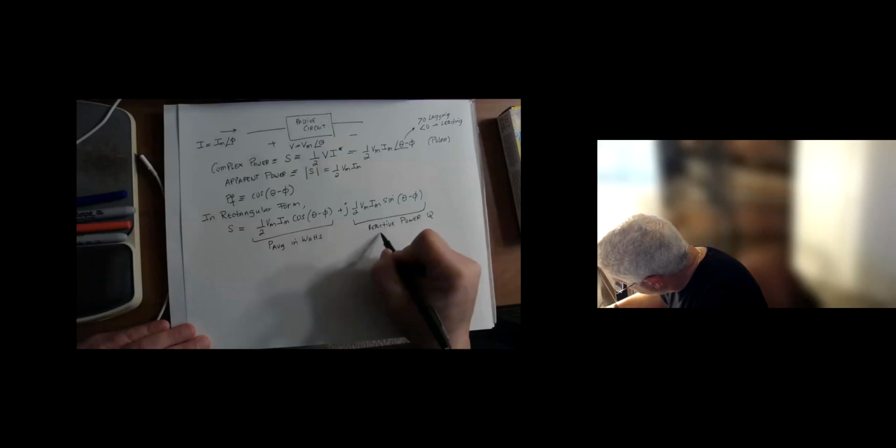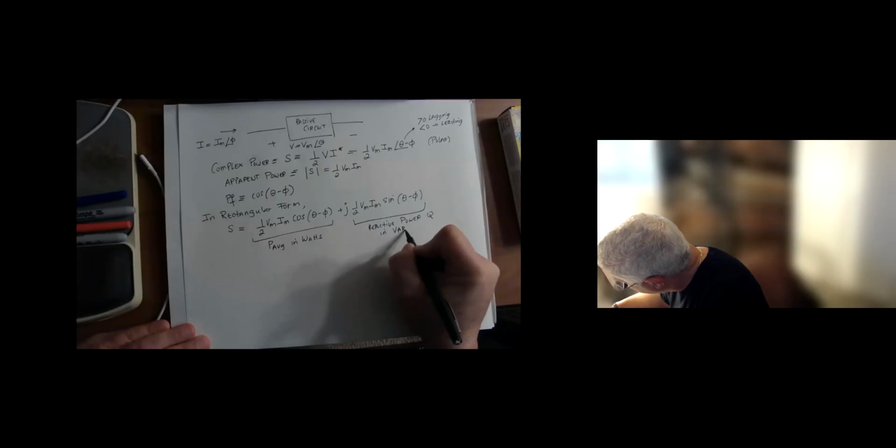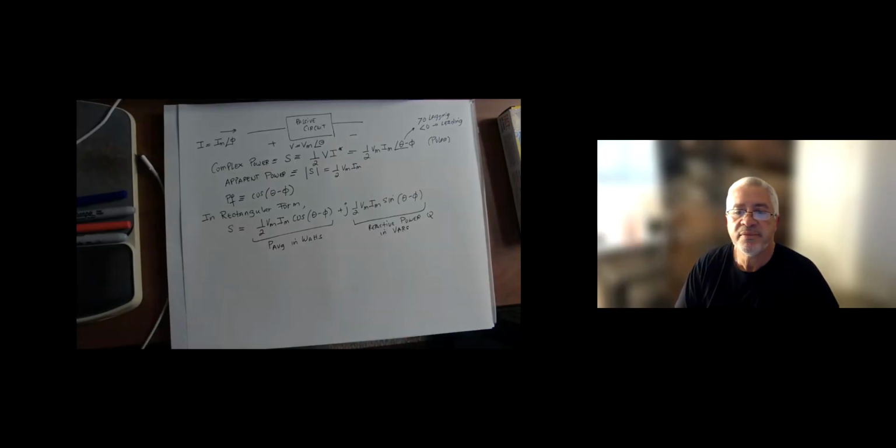The first term is the average power in watts, and the second is the reactive power Q in VARs, volt-ampere reactive. If Q is positive, the circuit is inductive. If Q is negative, the circuit is capacitive.